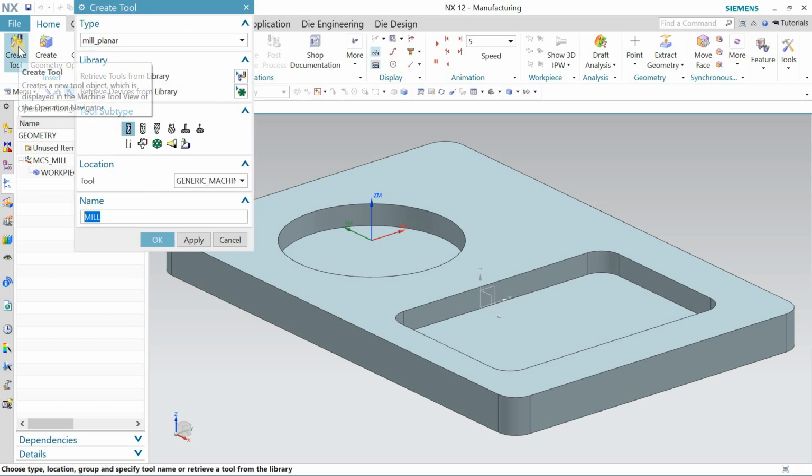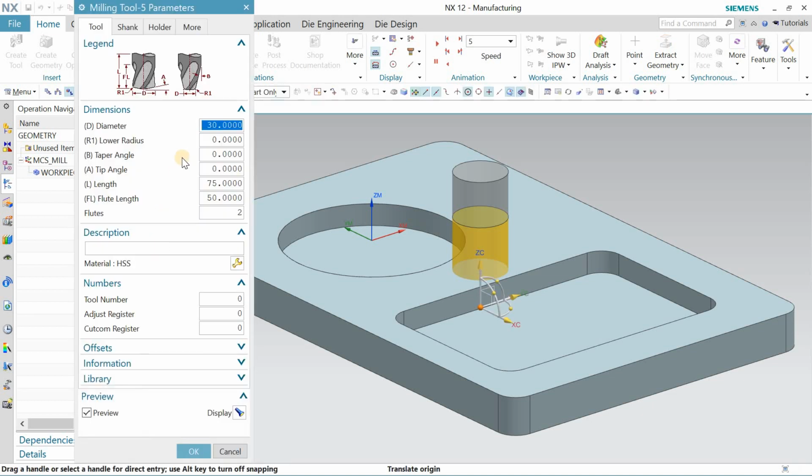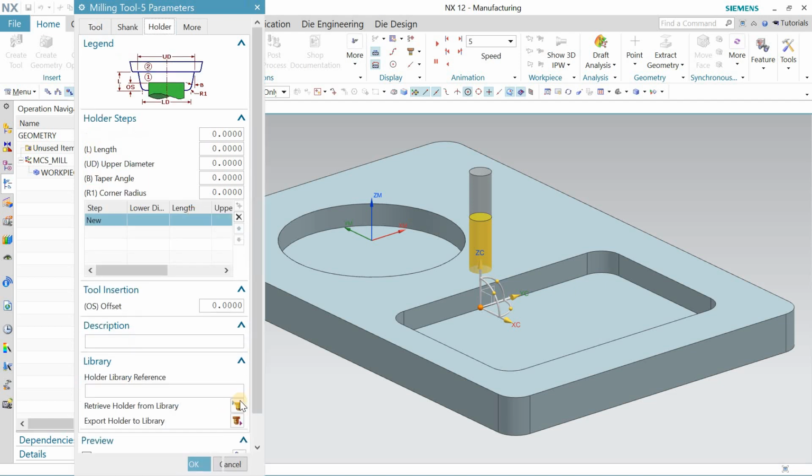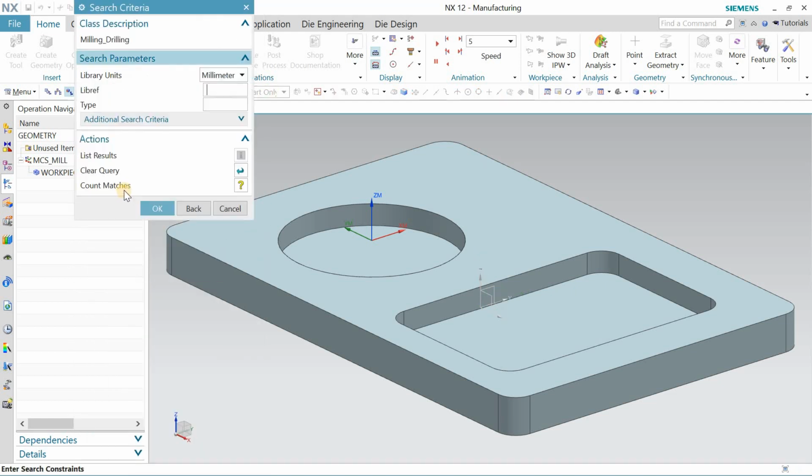Once you're done with this, then you need to define the work tool, with which you will cut the material. I'll click on the end mill, and then I will go for the 12 mm end mill. Click on the end mill and click OK. Now define 12, no corner radius, the length and width are properly defined for me, and I will just define a holder for milling.